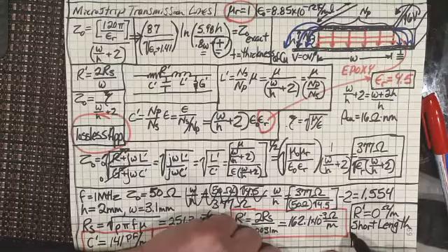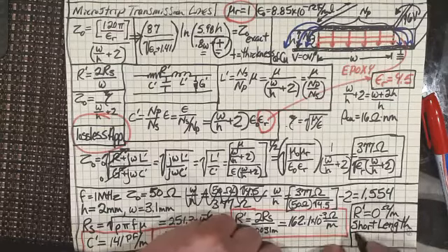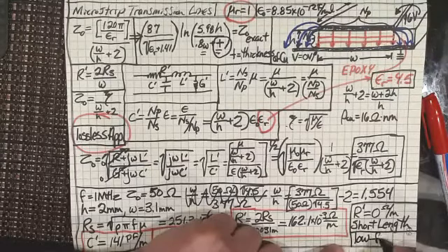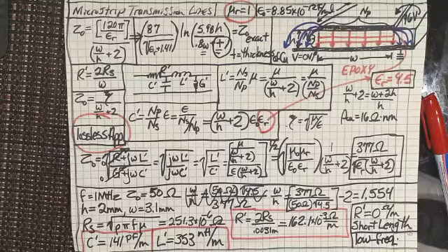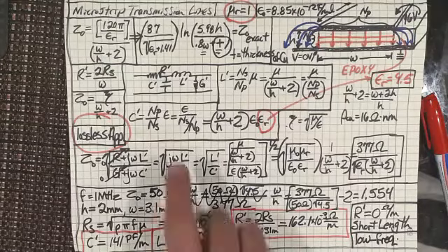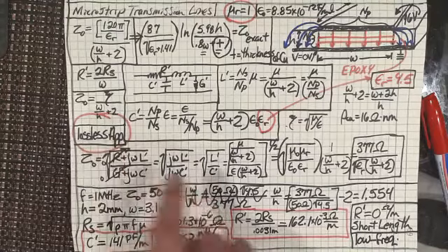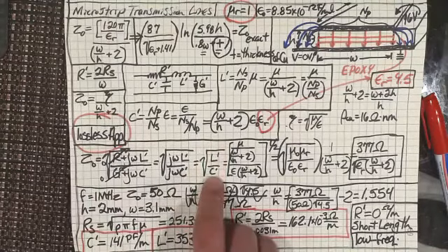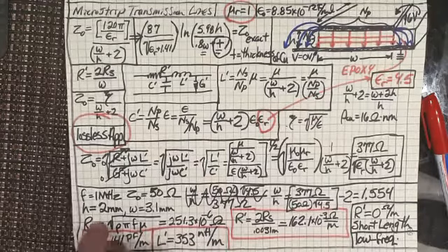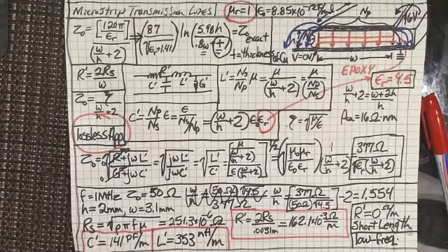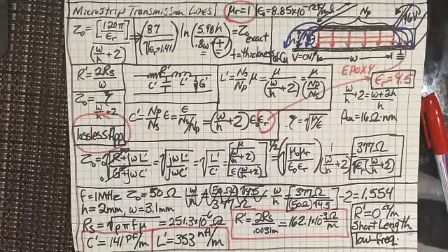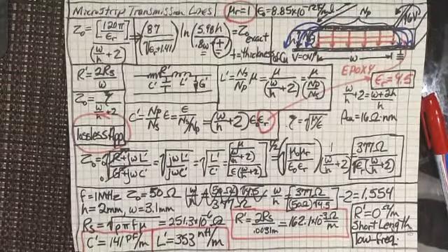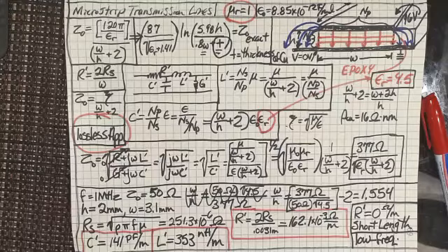What's the other reason? Low frequency. Low frequency or short length, we can make lossless approximation. And that's what I made here. That's why I made this lossless approximation here. What we're going to see working with these and coming up with the propagation constant now is that it doesn't matter. You're only going across your phone. You're only going across a computer's motherboard. So it doesn't matter. And you'll see that.